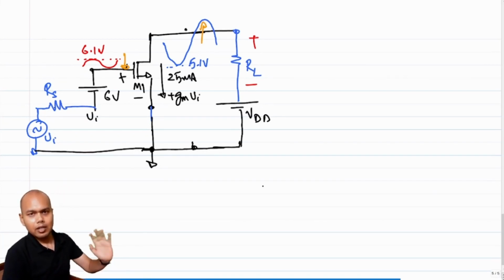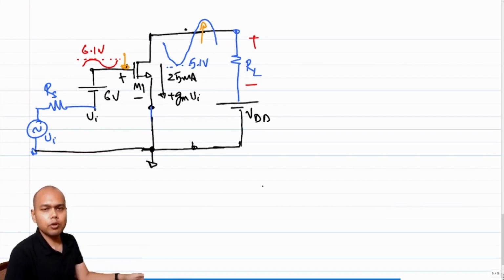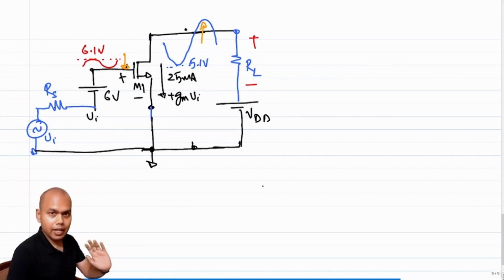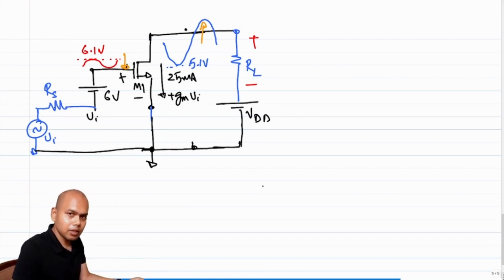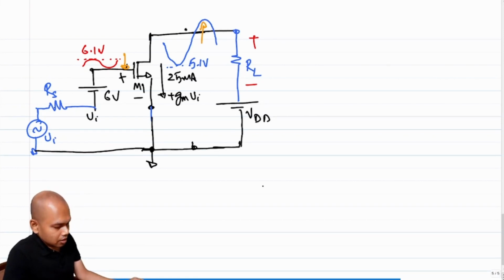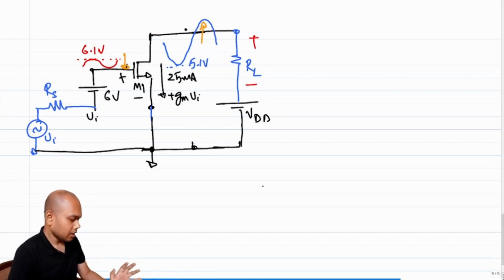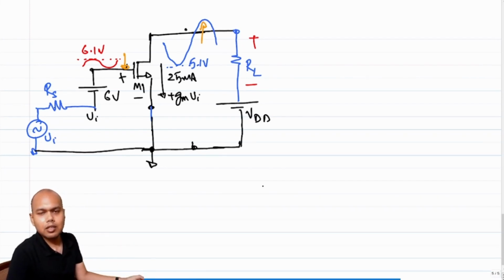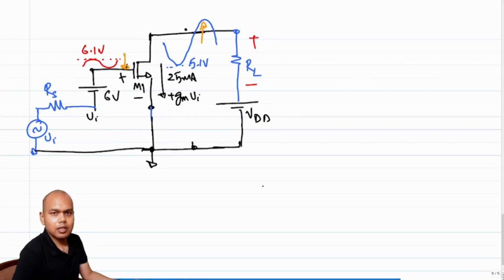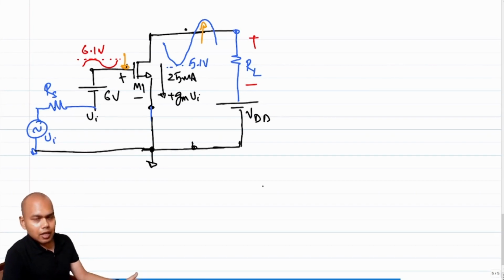So I am clearly pushing the transistor more and more into saturation. So getting into saturation is not the problem, but is there a problem on the input side? As in, is it at all possible that the transistor is getting cut off, right?